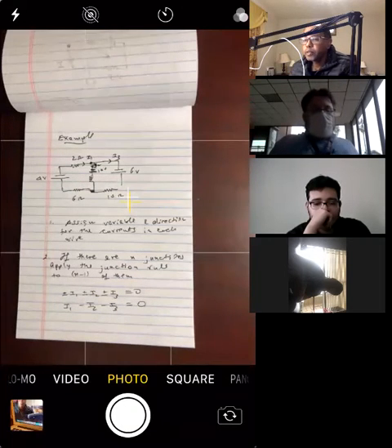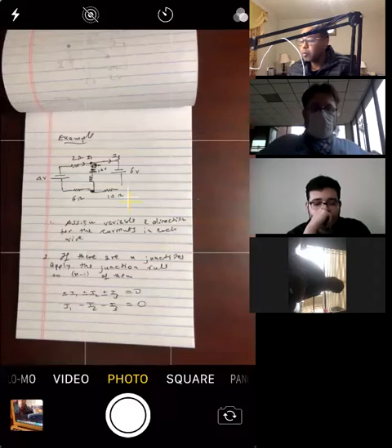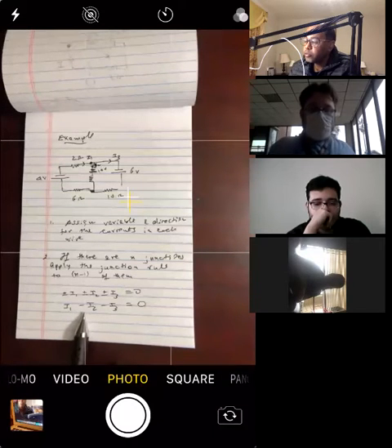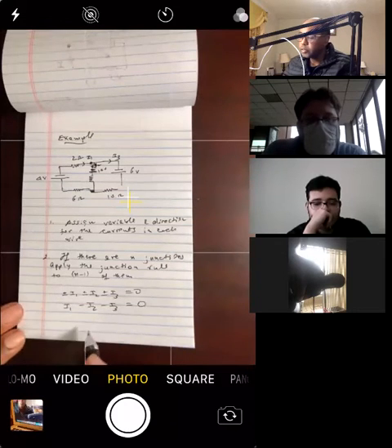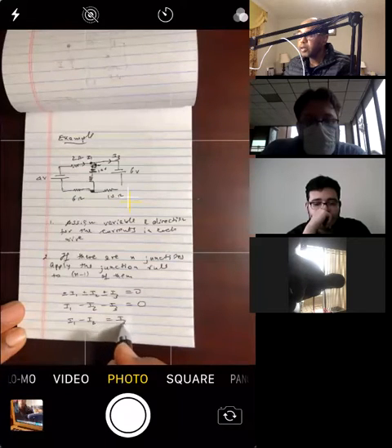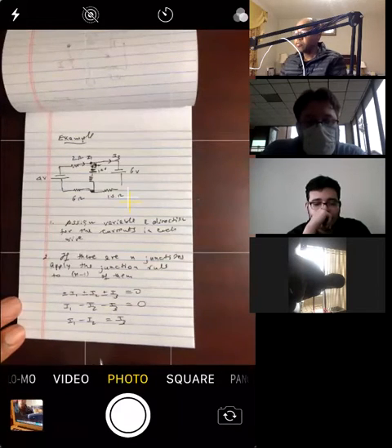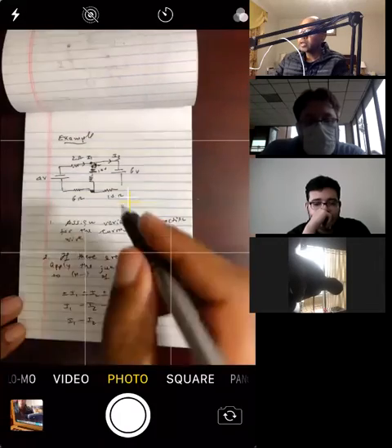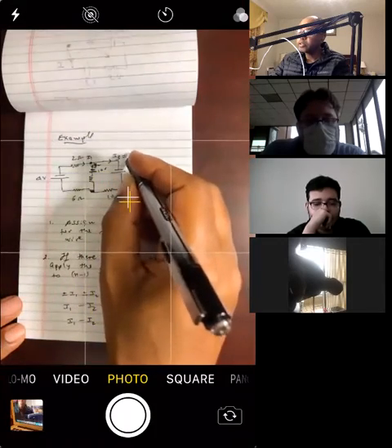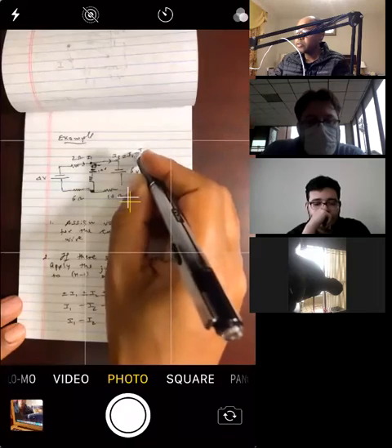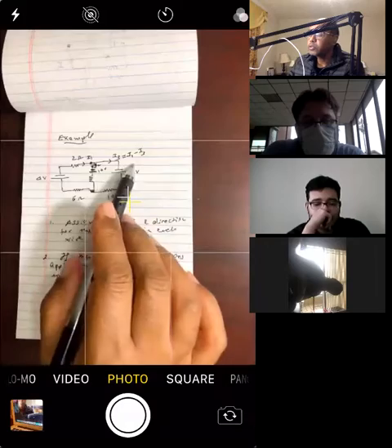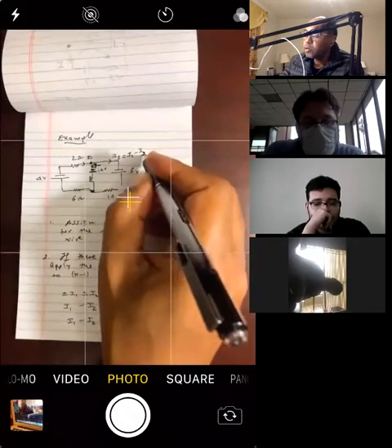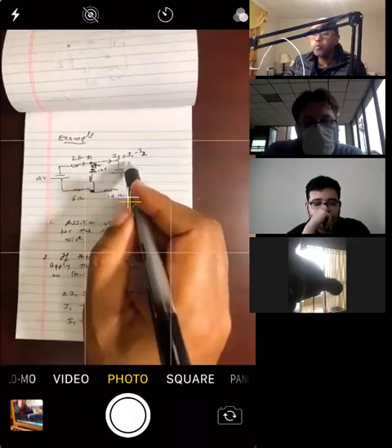Now we have 3 variables over here. That means you need 3 equations to solve this problem, but we can eliminate one of the variables right in the circuit. Okay, let me take I3 the other side. So I've got I1 minus I2 equals I3. Okay, instead of dealing with 3 variables, what I can do is I can replace this right in the equation. Instead of I3, I'm going to put I1 minus I2. Okay, so that I have to deal only with 2 equations. You see, so in the circuit I have replaced I1 minus I2.